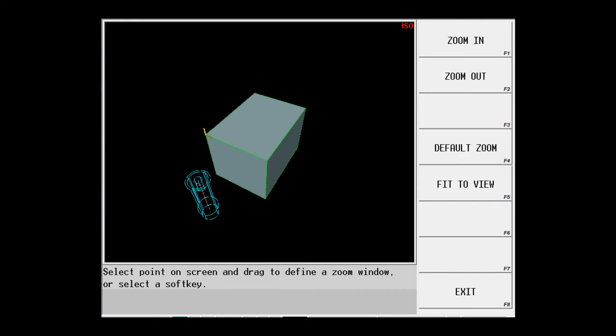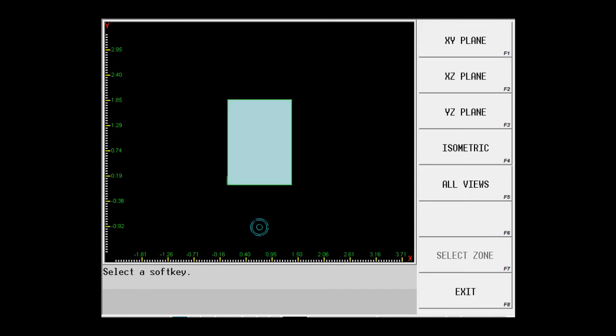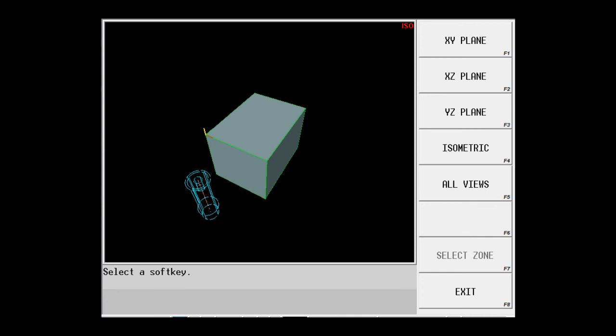Prior to this print, everything we have done so far in Intro 1 through Intro 5 has been using the bottom left corner as our 0 point. You see here that we're programming from the upper left corner of the part. So if you look at the way that this graphics is displayed, what is wrong? Is my hole in the wrong location, or is my stock in the wrong location? Well, in this case, I can tell by the little Cartesian coordinate in the bottom left corner of my solid model that it's my stock that's in the wrong place.